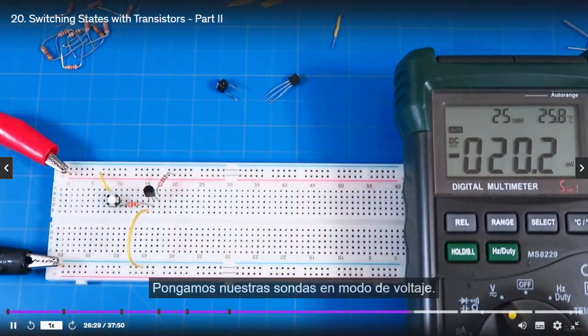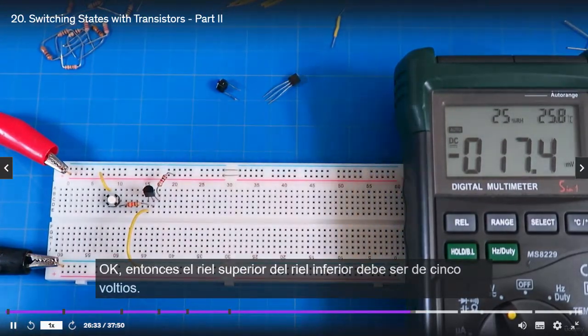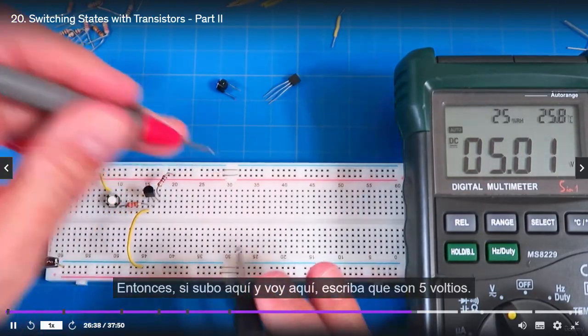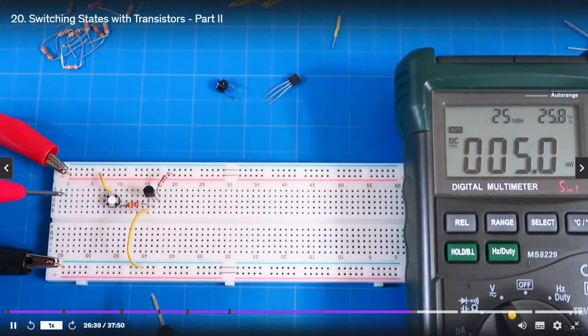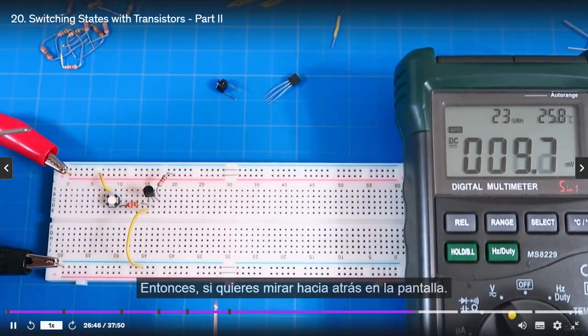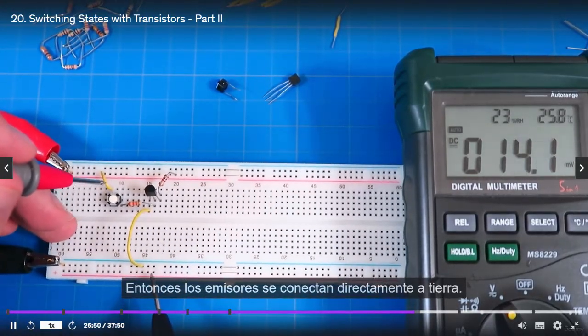Let's get our probes. We're in voltage mode. Okay, so the top rail and the bottom rail should be 5 volts. So if I go up here and I go here, that's 5 volts. Okay, and so right now, when the circuit is completely off, let's take a look at what some of these things are. So if you want to look back at the screen, the emitter is connected directly to ground.